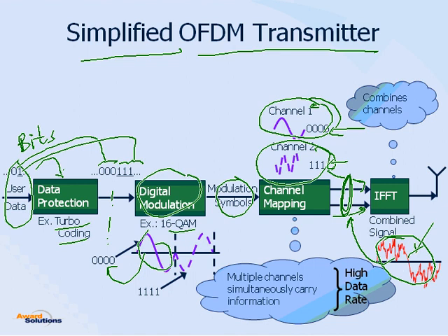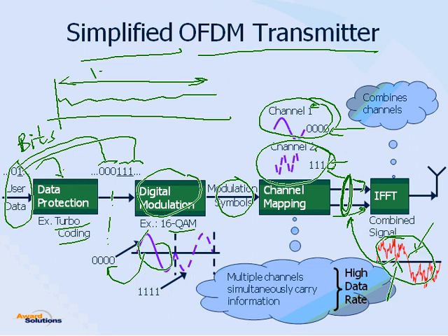So even though it looks like noise, it has inside all those orthogonal subcarriers with modulation symbols. This is similar to a CDMA signal. If you look at a CDMA signal, it looks like noise, right? Over the entire, let's say, 1.25 megahertz or 5 megahertz signal.